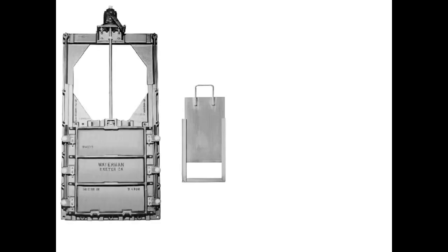You can see that it's basically just a sheet of metal in between a frame, kind of like a window frame, where the water is going to be pressing towards us, and it would be holding the gate up against the surface along the edges. And so not only have you got the weight of the water to lift up when a gate like this is open, but also there's the hydrostatic forces pressing the gate up against the frame. So it'd be very difficult to pull that up if there was very deep water.